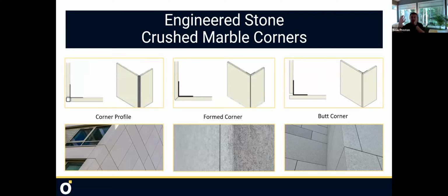with a rain screen. And if you were walking there, you know, the vulnerable joints on a rain screen that you can physically see into are vertical joints. So how do we mitigate the visibility and the fact that they're usually not level and plumb? How do we get a nice looking corner on this expensive facade? So most rain screens say, well, pick which one you want plumb, pick which side you want the corner to show, and tough luck.